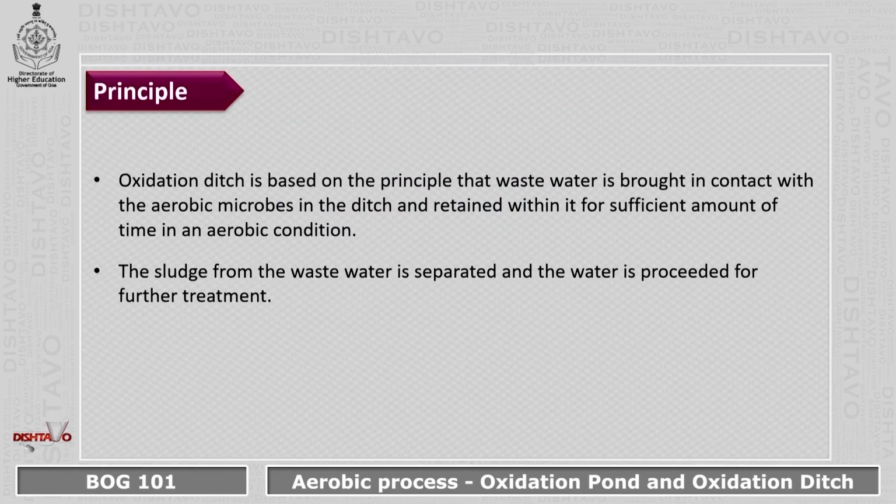Oxidation ditch is based on the principle that wastewater is brought in contact with the aerobic microbes in the ditch, retained within it for a sufficient amount of time in an aerobic condition. The sludge from the wastewater is separated and the water is then proceeded for further treatment.